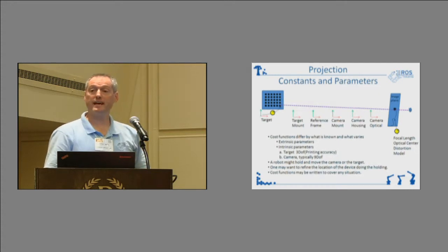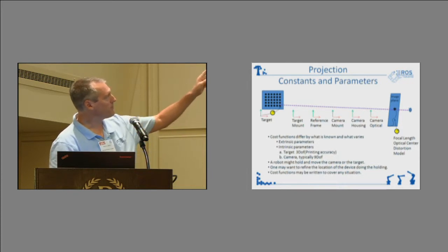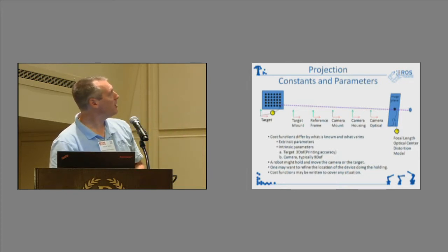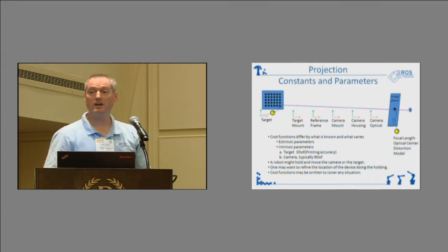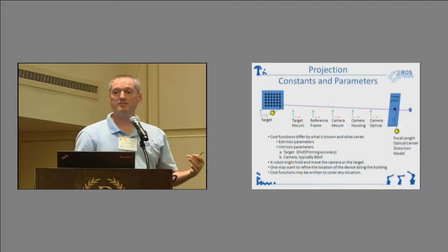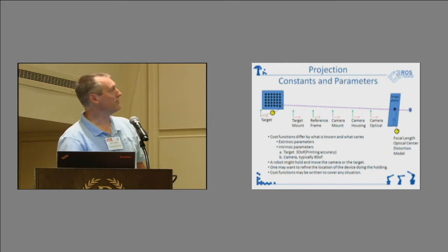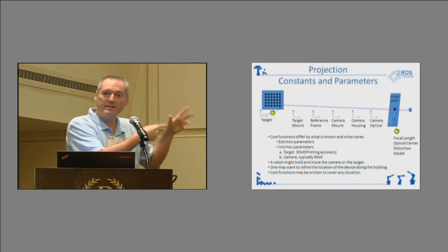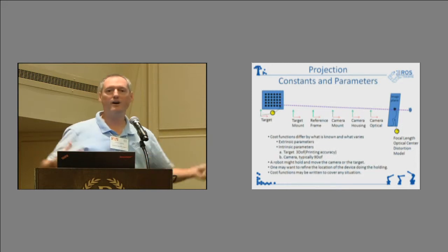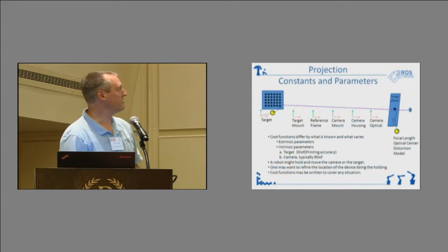that is known. In this case, in the cost function, it's passed in as part of the constructor, whereas the transform from the base to the target is unknown. So those are parameters that are adjusted by the optimization procedure. So essentially, all the different calibrations that I can think of include these more or less 5 different coordinate frames, and basically projections or transformations between all those frames, and all the different combinations thereof that you can think of for your calibration that you're trying to do.